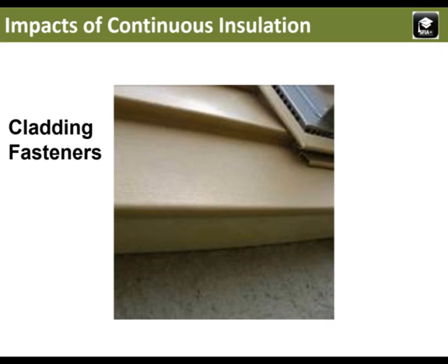The fasteners have to be long enough to account for the thickness of the insulation, which again may be from 1 1/4 to 3 or more inches. Based on research supported by SFIA and others, the International Building Code adopted a set of prescriptive fastener tables in 2015 for attachment of cladding over foam insulation.